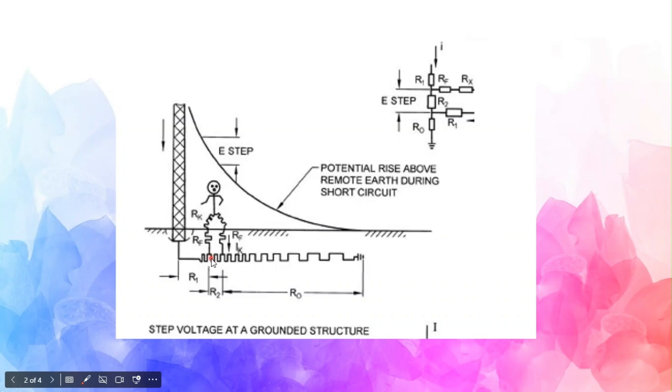Now, what is the solution to this? Let me first tell you about this potential difference. This potential is called the step potential. These things are applicable particularly in high voltage substations. As a designer, you need to limit this step potential and touch potential. I'll come to touch potential in the next slide, so that no one gets shocked even if they are standing, spreading their legs, just beside a ground.